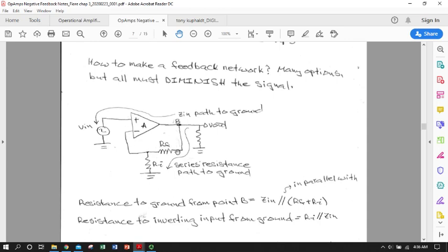And by the same token, you can calculate the feedback voltage, or the difference in the output versus this point, by the voltage drop over RF. So RF and RI both combine as a voltage divider to change the voltage from this point to this point, but RF is the one that is basically selecting how much of V out comes back in and is fed back in. So a little bit different function, that's why it's called the feedback resistor.